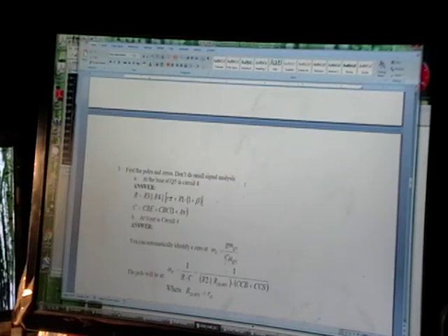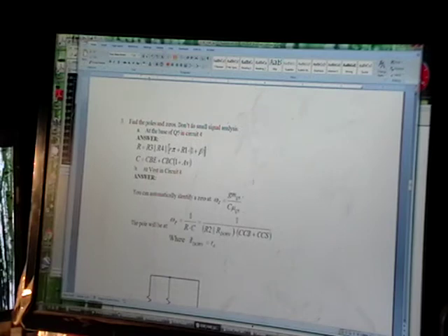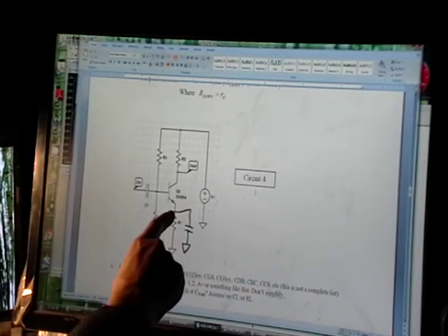Okay, I forgot about this one. Okay, then great, we found capacitors. The reason we're trying to find capacitors is to find poles. So here's circuit 4, and I put a bypass capacitor in here, which means this node doesn't move.